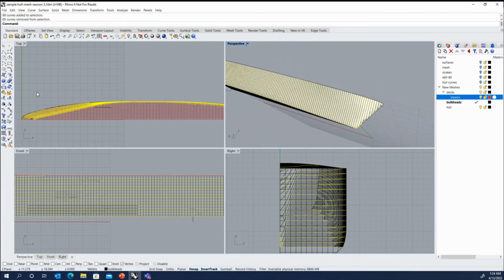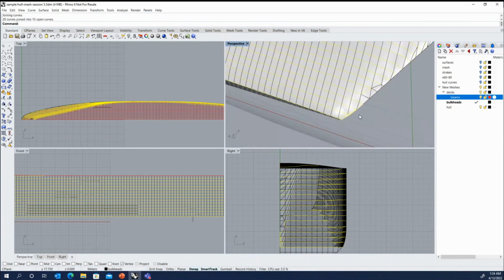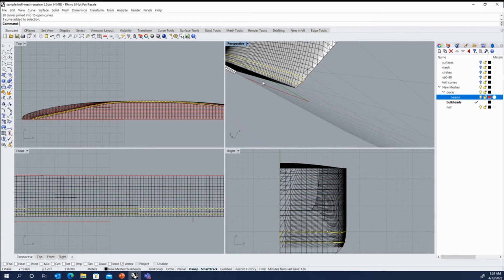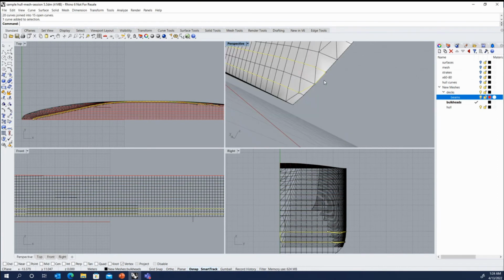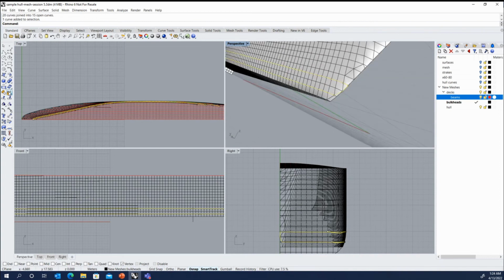Since they run parallel to each other, we can go ahead and join them, and they should get merged back together. Now, a couple of them down here, you can get some odd connections. That obviously is not the stiffener trace we want. So the easy way to correct these, and this is kind of a handy thing to do, is to just explode the polyline, deselect something to break it, and then rejoin it. So our traces are pretty much intact.